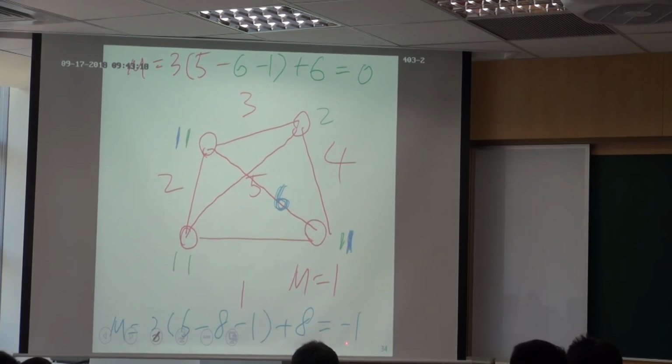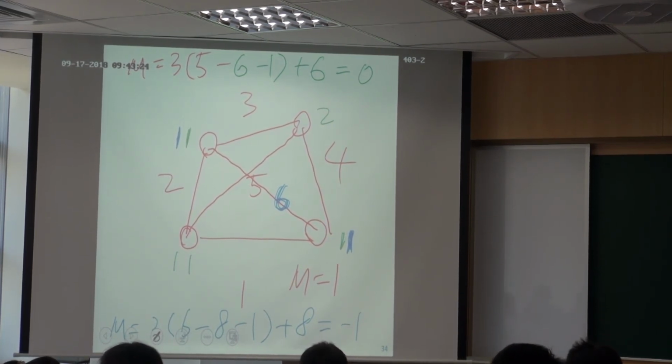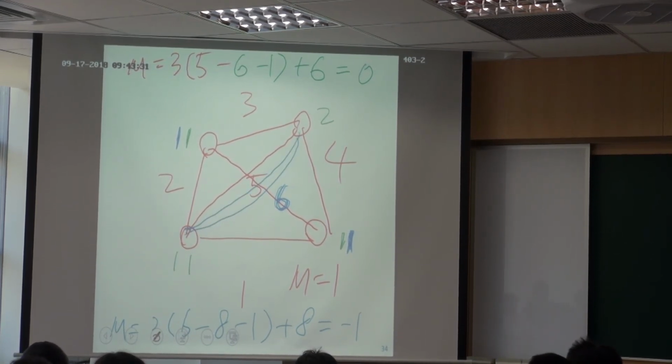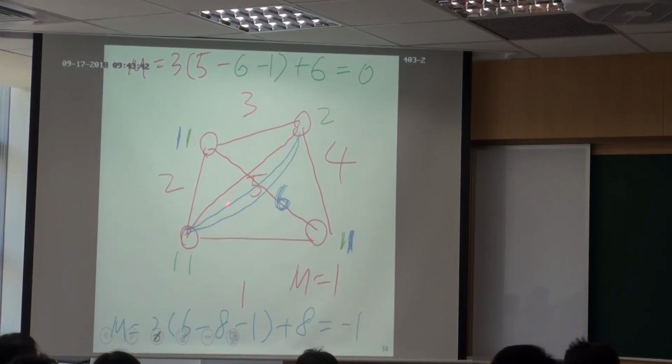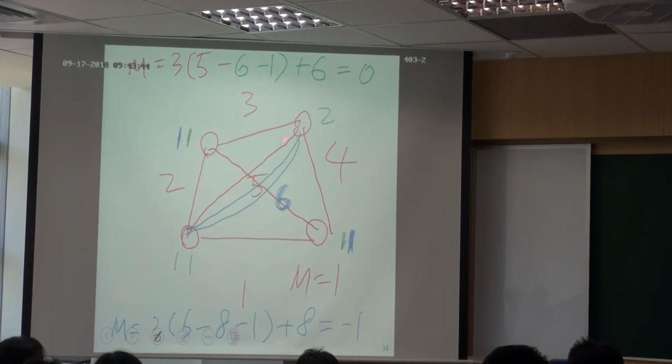It's not expected to have a minus value here. But if you just use the equation, if I add one more link here, it didn't add any more constraint to this linkage because it's originally constrained. It's originally not going to move. But for every link I add here, you will get a minus larger value.